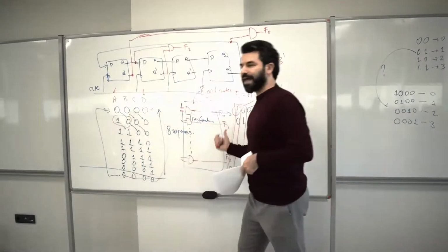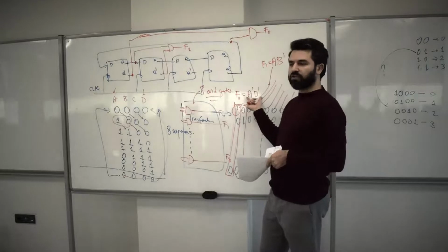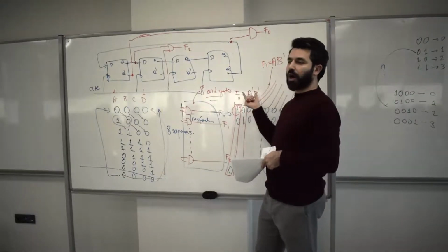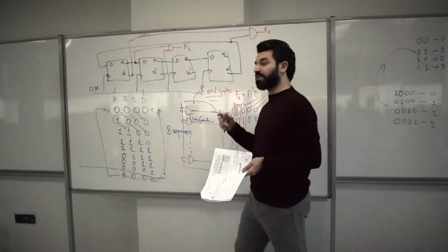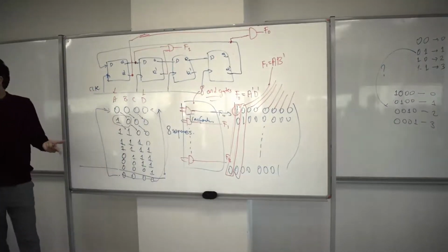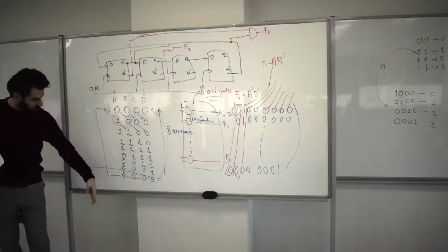Go ahead and draw a truth table. You can figure out that the Boolean function that corresponds to that Karnaugh map is going to be as small as this one, A prime, D prime. The way that I described is easier because I looked at these inputs, and there are don't cares, by the way, right?